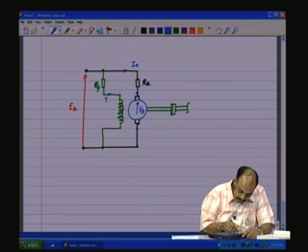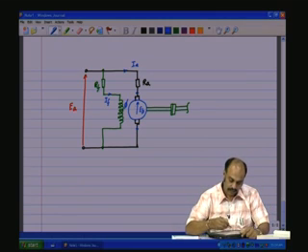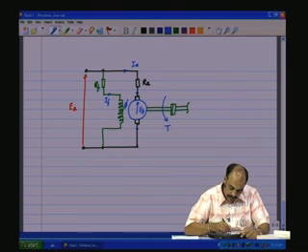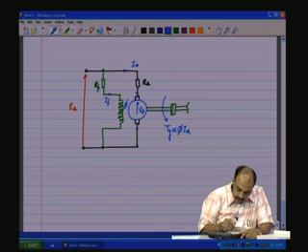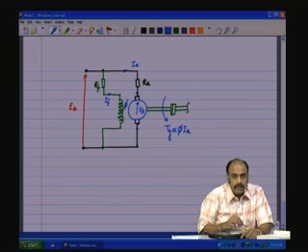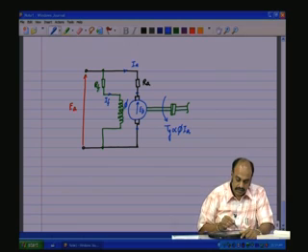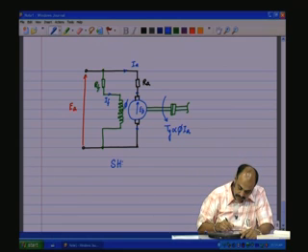There is a field current IF which flows through the field coil to produce flux phi in the machine, and the torque Tg which is generated is proportional to phi and Ia. Now, you see this field coil, what is shown in green is the field coil which is connected across the terminals of the motor, and what is applied is the same voltage whatever is applied to the armature. The EA, what is applied to the armature, is also applied to the field, and this is called the shunt connection. This is a shunt field motor.